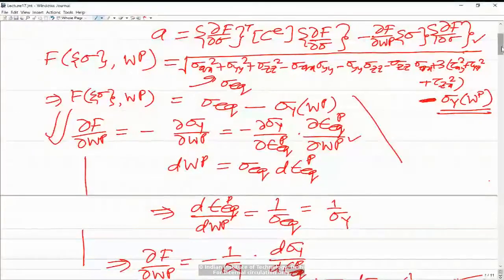You need the plastic strain over there, so all those terms will be substituted there. Once you solve that equation, you get the incremental displacement vector, then you have to do all these calculations to calculate the plastic strain, back stress, and the stress itself, and all these calculations would be going on within that iteration.